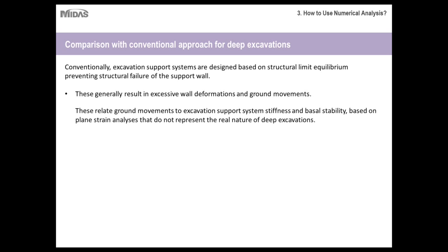These methods generally result in excessive wall deformations and ground movements. They relate ground movement to excavation support system stiffness and basal stability, which are based on plane strain analysis that does not accurately represent the nature of deep excavations. Deep excavation behavior, as we have seen all throughout this presentation, is completely different. We are dealing with a different structural system altogether, so these methods don't accurately represent it.